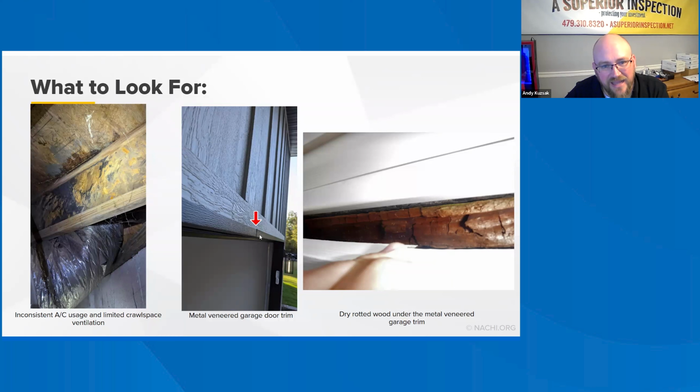And when they did that, they did not adjust the trim. Honestly, if they would have kept the metal off, it would have been fine. But what happens is, when it rains, moisture penetrates through the joint, and then it rots out that upper door trim, and this is what occurs. So after about 8 to 10 years, this whole thing is going to be rotted if they do not address this problem.